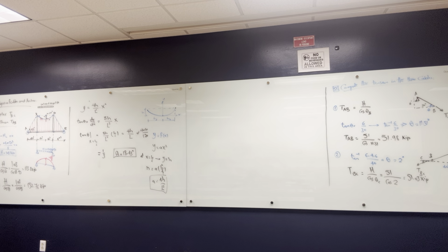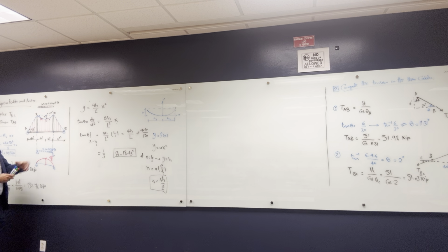Do we include the self-weights of the cables as well? What was that? The self-weight. Yeah, well, some people neglect the self-weight, but this one, you can't neglect the self-weight of. That's a really huge cable. It depends on your bridge. Sometimes the diameter of this cable is like 1 meter.